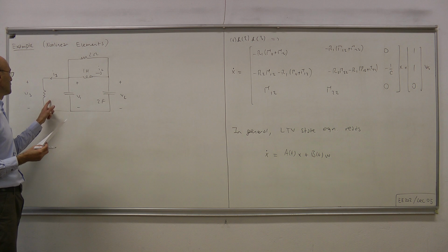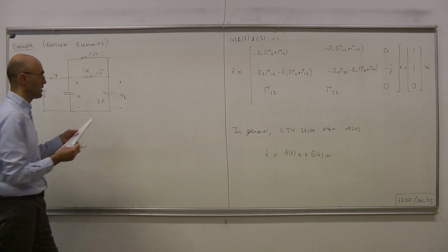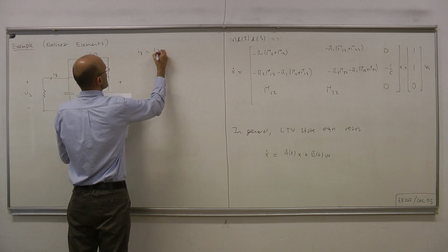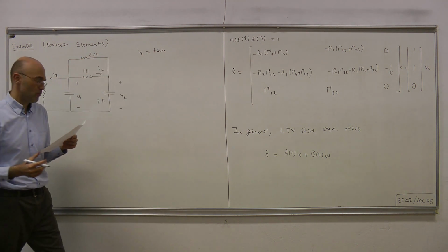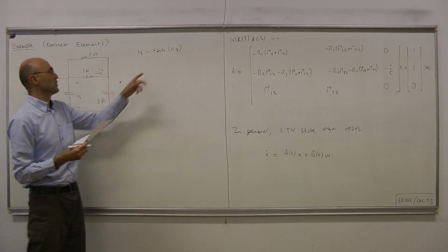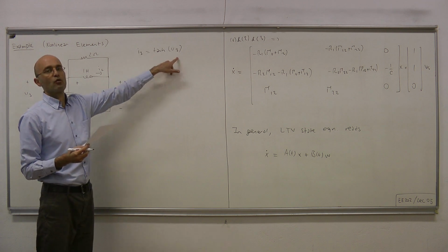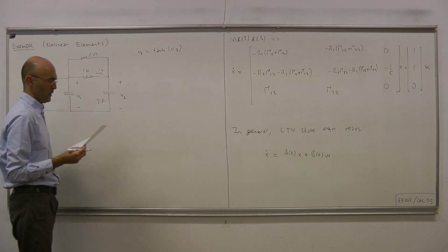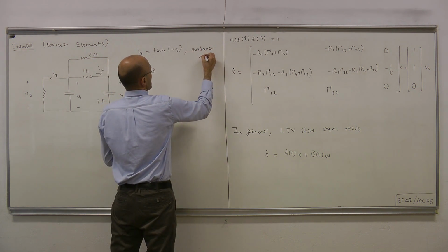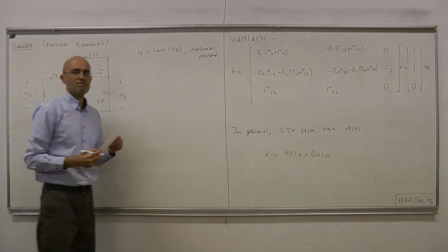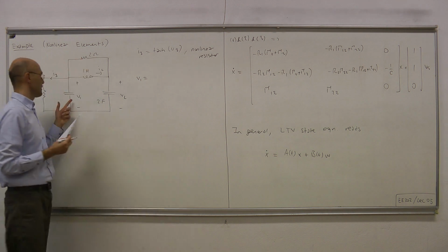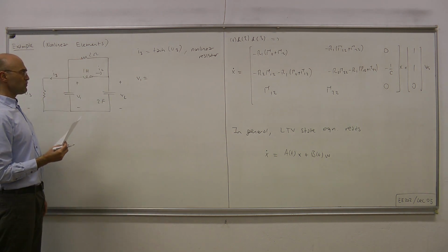Okay. So we need the terminal equations for those two components, and they're given as follows: I3 equals tangent hyperbolic V3. Okay. So the dependence of the current on voltage is nonlinear. This is a nonlinear resistor. And then we have here the nonlinear capacitor.